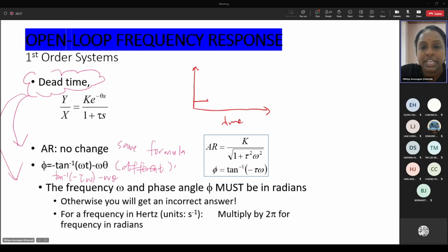But if you notice, before I give the signal, this is the input, okay? Before the output response is out, there will be some lag, okay? Some dead portion at this part. We call it the dead time response.